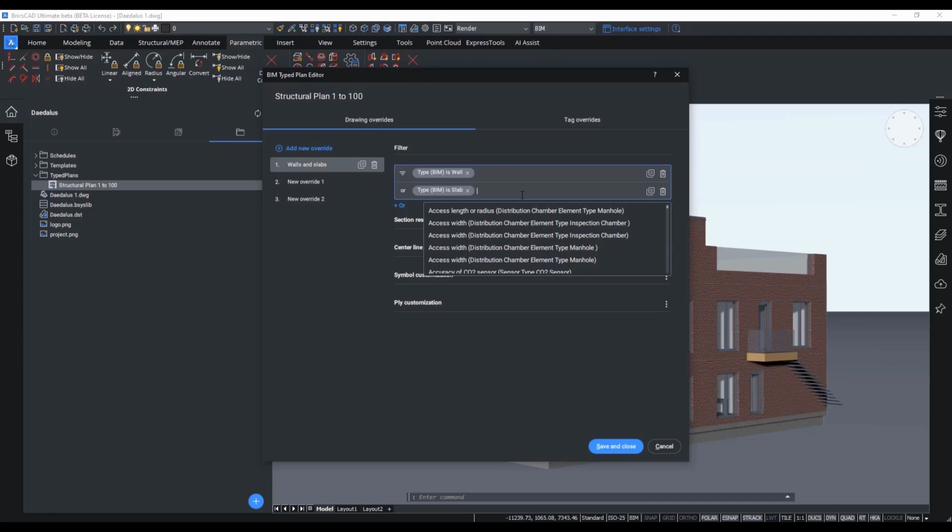As such, we can make more and more filters. And in general, it's best to start with your most specific filter lines and then work your way to broader and broader filter lines. You can even leave your last filter line so generic to encompass all other elements, by just not specifying any filter expression in it, meaning all the rest, which hasn't been filtered out yet, will be customized like the last line specifies.